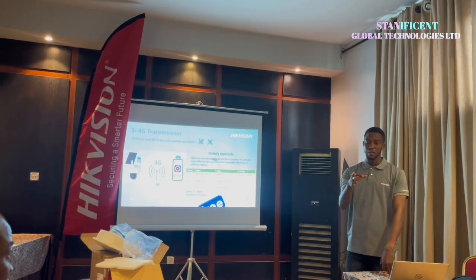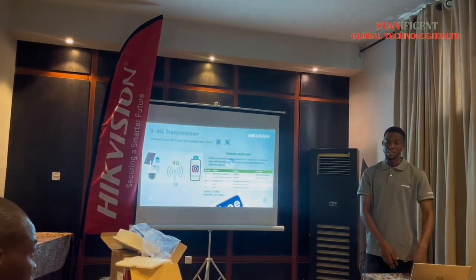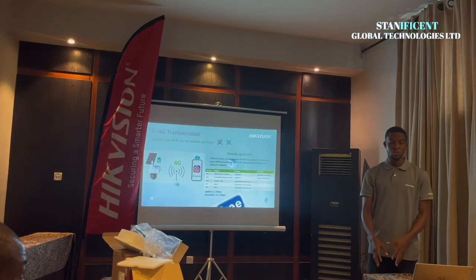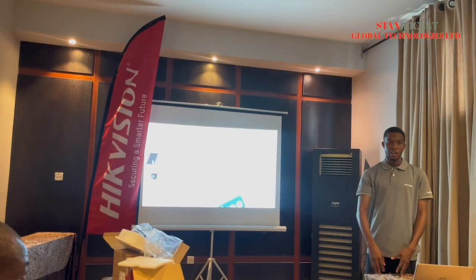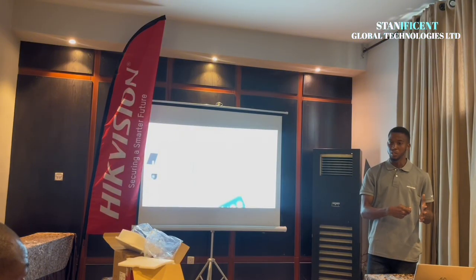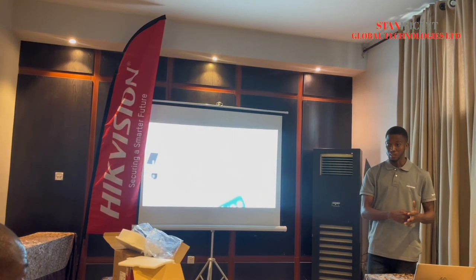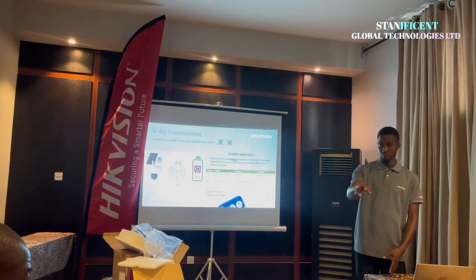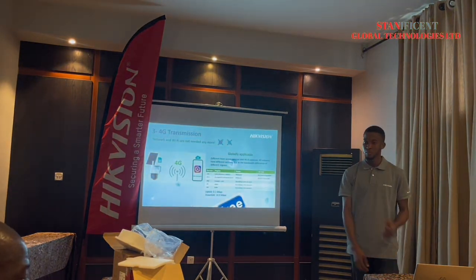You can log into the backend of this using SADP. I don't know if people are familiar with it. Yes. So with the use of SADP, when you log into the backend, making sure that this is connected to a switch that has internet, on the interface, you'll be able to scan the barcode and then you add to iConnect.